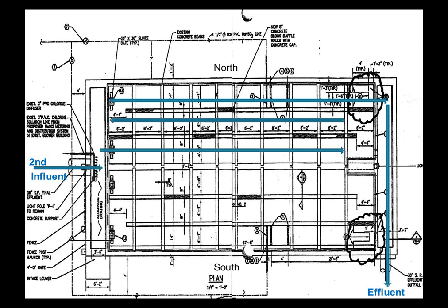That's key here because once you have a rainfall and you have that much water coming to the plant, we have to go to bypass and we have to meet discharge limits. To give you some numbers on the latest discharge, we were seeing about 690,000 fecal CFUs per 100 mL against the fecal limits. In 9 minutes' time, we got down to 440.